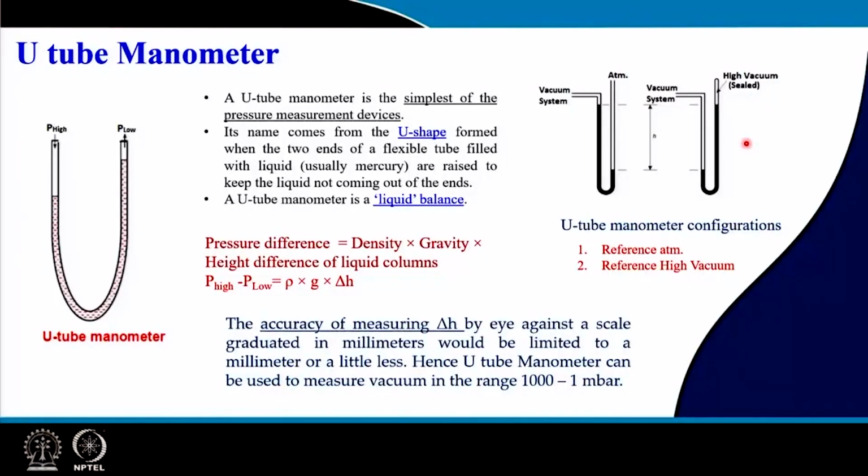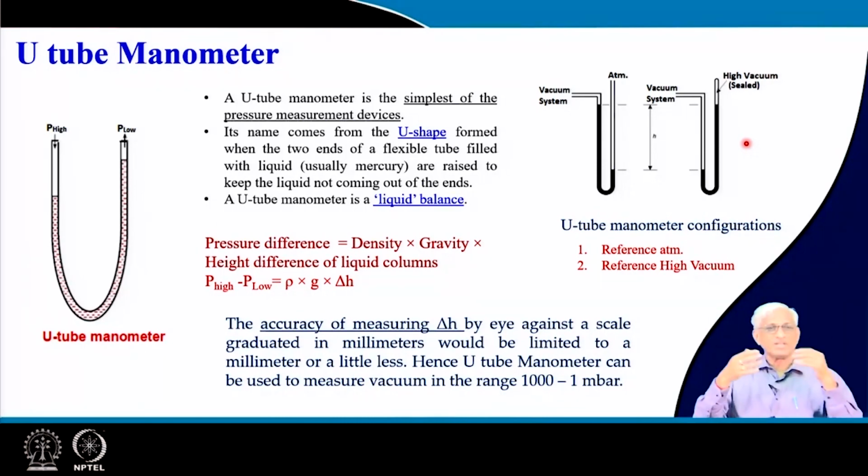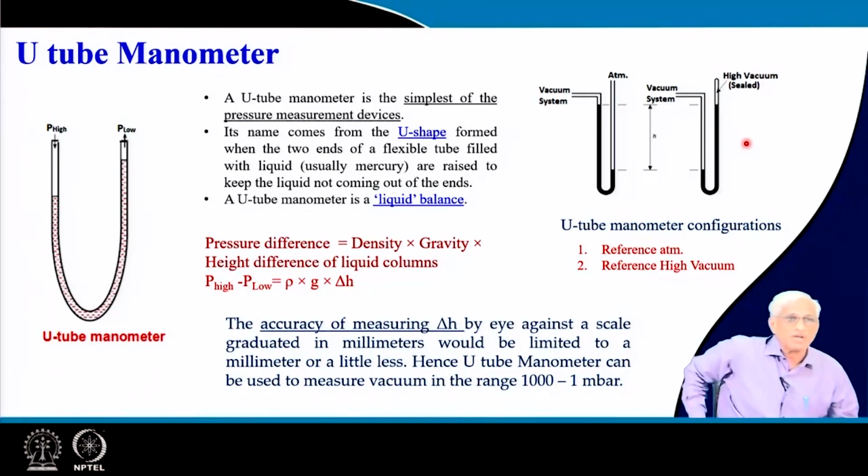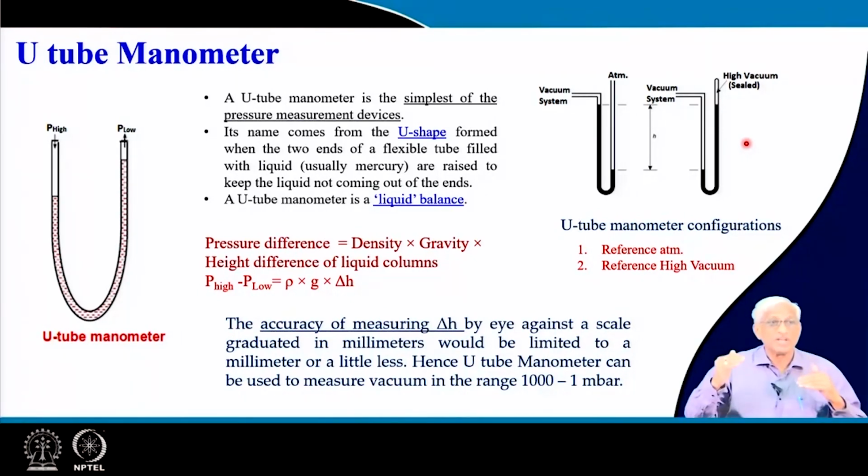Okay. So, once it crosses 10 millibar, the difference is already 750, because one side 760, other side is 50, 750. So, you will have to be careful. If it goes to 1, 759, if it goes to 0.1, 759.9, but you cannot measure 759.01, which is just a normal vacuum with respect to a rotary pump. 759.99, we cannot do this.